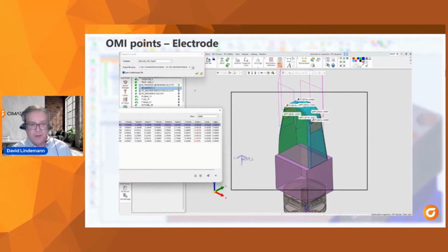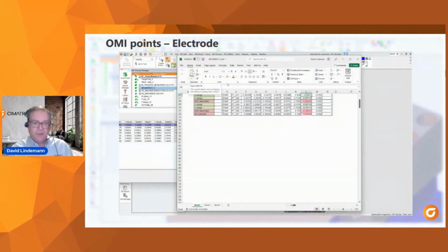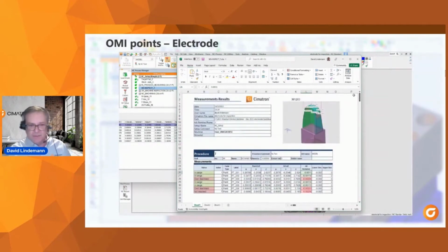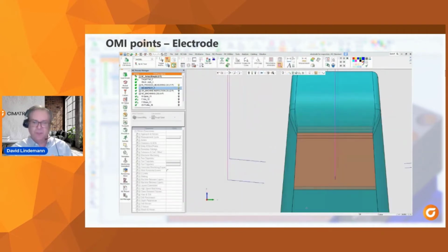What if it's not quite right again? I saw I overcut some areas. Am I going to have to drop everything and recut it? What do we do so that we don't have to waste that graphite? Again, I didn't take it off the machine, so I can make my adjustments here using these inspection points to get the knowledge of what's actually happening while cutting it.